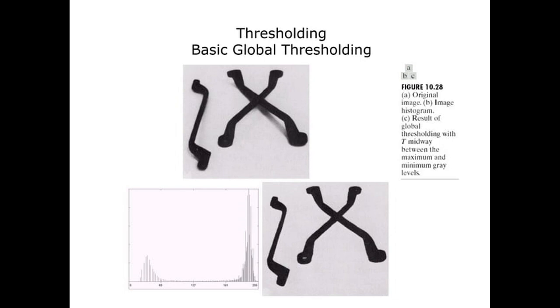Similarly, what is this thresholding operation? You see the image. The first figure represents the original image and the second one is the histogram image. For this we also have two profiles. We have the black color near zero intensities, and near high values we get the white color intensities. And after thresholding, this is global thresholding. What does global mean? If you are applying the thresholding procedure to the overall image, then it is called global. If you are applying it to only one part of an image, then we call that local thresholding. Here, after applying global thresholding, we get the output like this.